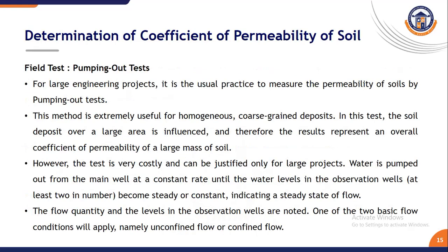Here this one is different, the field test, also called the pumping out test. Pumping out tests are conducted for large soil masses. Water is pumped from a well and the water level in observation wells is measured. However, this test is very costly and can be justified only for large projects.